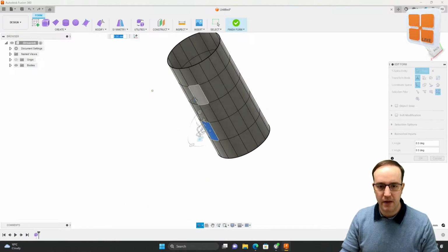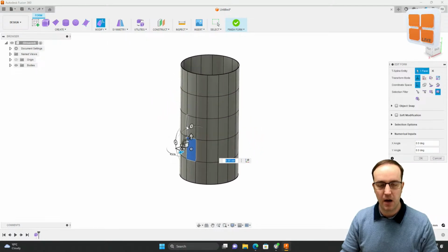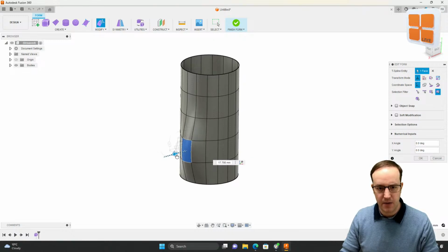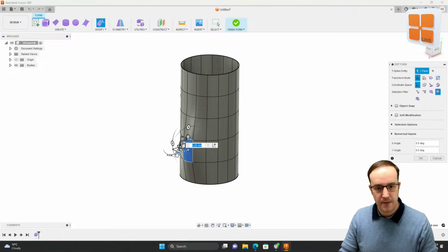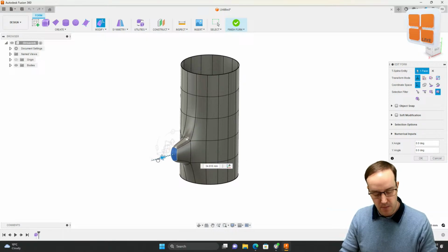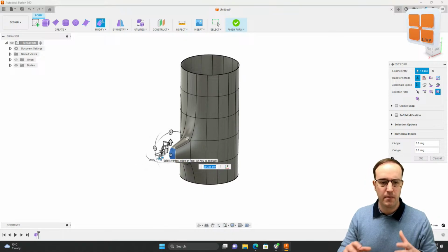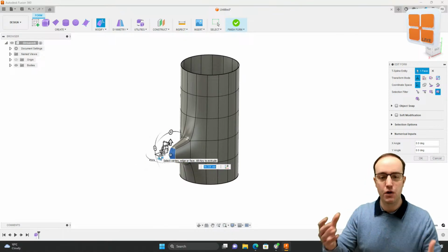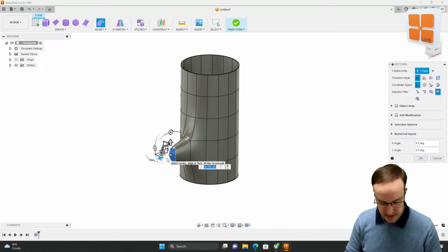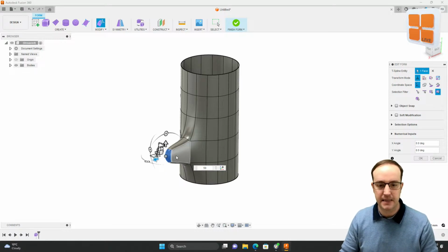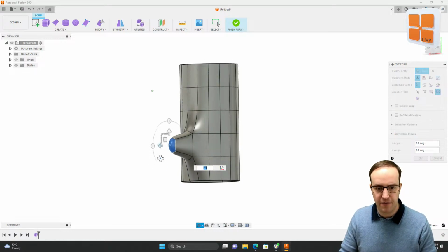Okay, so everything that you do starts warping and controlling. But as well as warping and controlling this, we can also come in and start adding to it. So if I just move these, it will sort of stretch the material. I'm just going to stretch this by about 10 millimeters to show that I can be quite specific. But then if I hold down my Alt key on my keyboard and pull that out, it will start giving me an extrusion. It will give me a new face. So I can pull that out, and again, I can be doing this by eye, or I can type in a specific distance. So let's go for about 50 millimeters. And that will extrude that out about 50 mil.